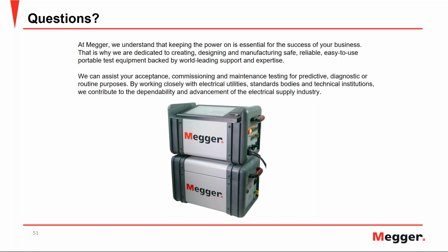So when you're evaluating your power factor values, you not only need to look at the capacitance, but also the leakage current and watts loss, and you need to review all those 4 parameters together. When you talk about the range of the capacitance and leakage current, that would vary from one asset to the other, and also depends on what you are testing and what the previous values have been.